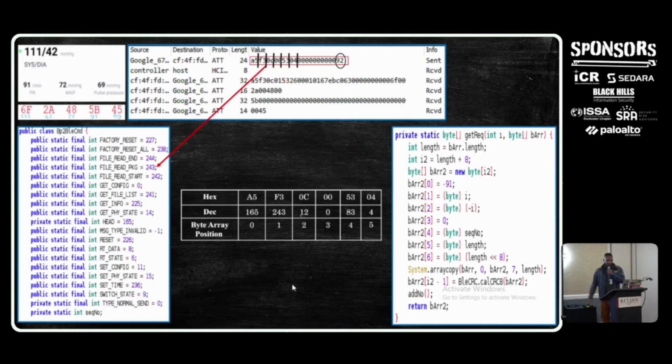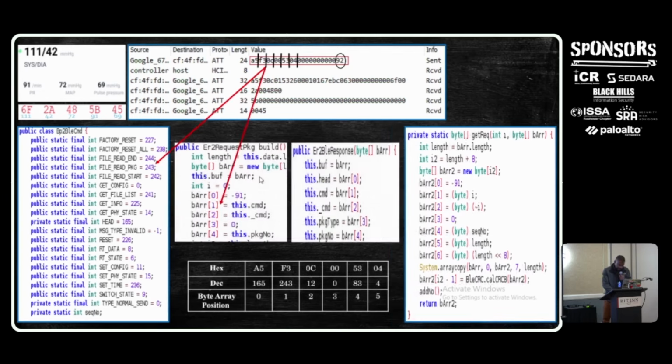We have another function called BLE Command. So now we have a bunch of commands. So at least we know the first part is my phone making a request to the blood pressure monitor. In this case, the request is the read package, 243. But at this point, I'm still not entirely sure that's a coincidence. This app has hundreds of functions, so I'm going to move forward to see if everything matches up.